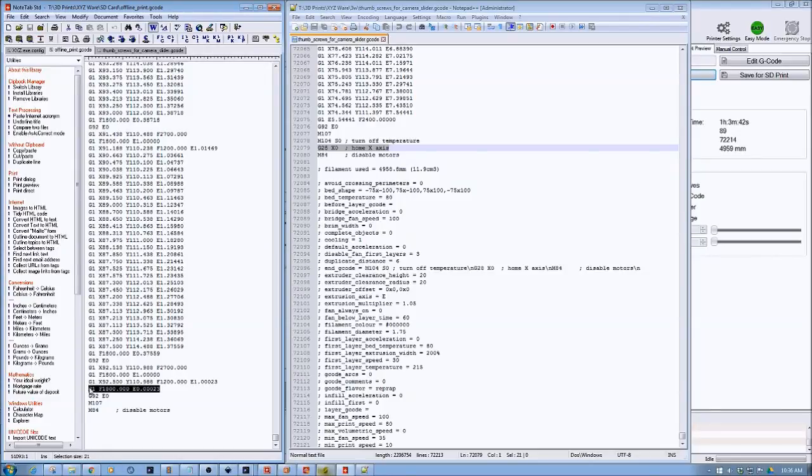basically G1. One of the things that I've been seeing on the internet is that the regular, because the Vinci's work backwards. So in other words, the print bed moves down as it's built, where most Prusas, etc., the print head moves up. So intrinsically, it's moving out of the way as it goes up. So there's no command in here to lower the bed to a position, so I've got to take a look. I'm a little bit rusty at the G codes. I'm thinking that something in here after the G92 E0 needs to be added.